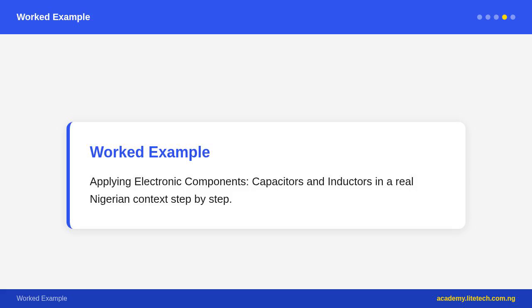Types. Electrolytic, large capacitance μF, polarized equals has positive plus negative terminal equals must be connected right way round, cylindrical, power supply circuits. Ceramic, small capacitance pF to nF, not polarized equals can connect either way, disc or chip shape, high frequency circuits. Film, reliable plus stable, audio circuits. Variable, capacitance can be adjusted, radio tuning.